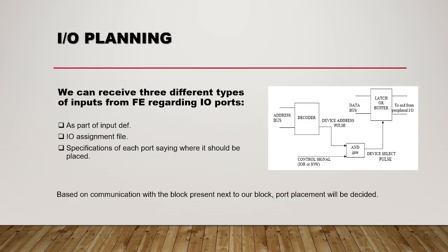IO planning means we can receive three different types of inputs from FE regarding IO ports. What are these? From the DEF file, from IO assignment, and the specifications. Based on this, we need to do some IO plan. So we need to do this IO planning.